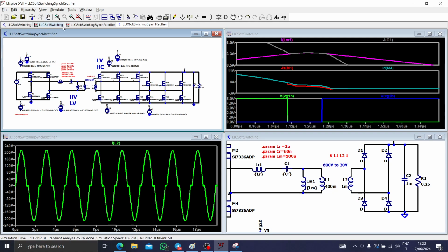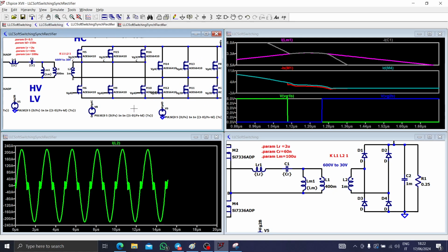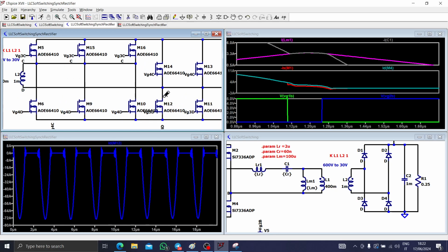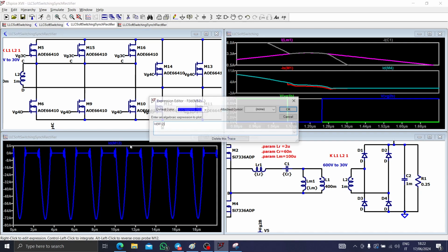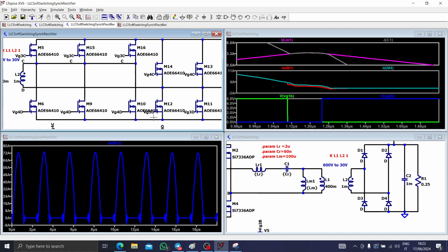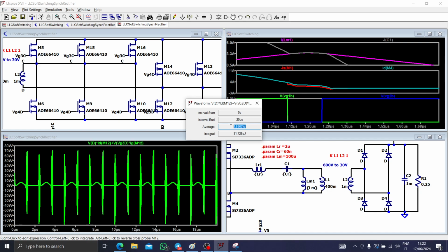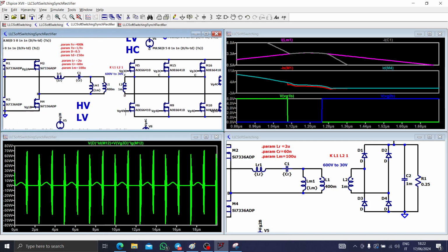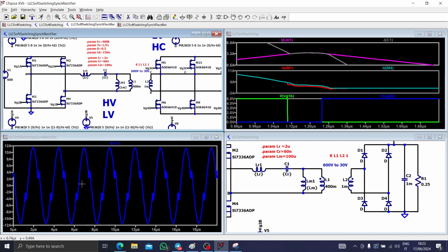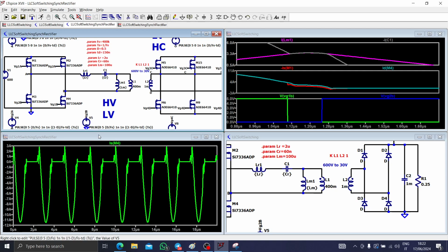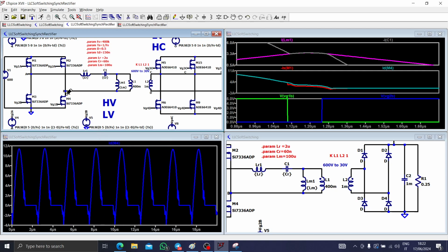So let me run the simulation again. And we shouldn't have any more 200 amperes flowing into... we have 80 amperes, which is feasible for one MOSFET. It can be feasible. And the dissipation of this is 1.5 watts. So we have reached a feasible dissipation in this case, and we have kept all the waveforms more or less. We have kept all the waveforms of the switching frequency.